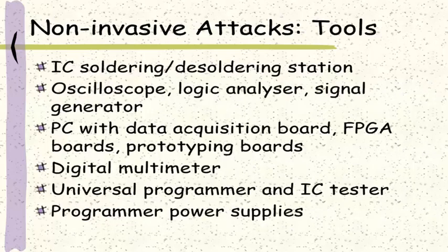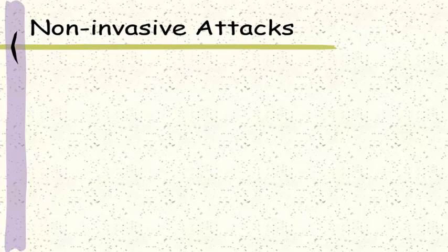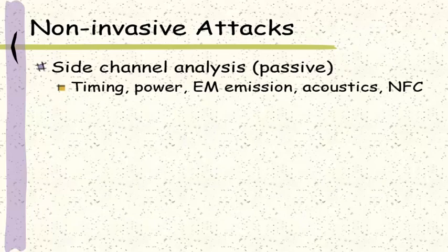These are the set of tools and equipment that might be useful for non-invasive attacks. There are 4 types of non-invasive attacks. Side channel analysis. This is the only passive attack, as it only monitors the chip's execution and collects some measurements.